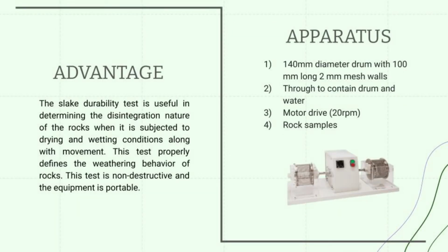Next, the advantage of this test is that it is useful in determining the disintegration nature of the rocks when they are subjected to drying and wetting conditions along with movement. This test defines the weathering behavior of rocks. It also is non-destructive and the equipment is portable.